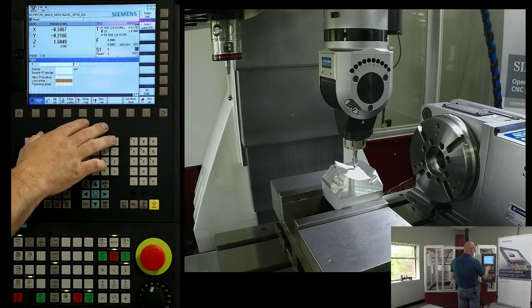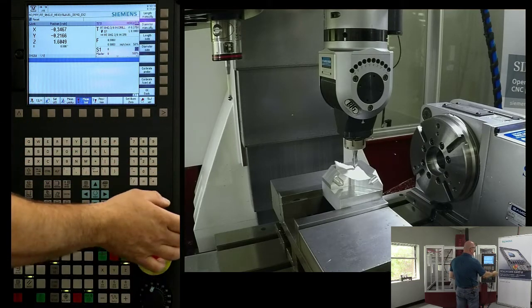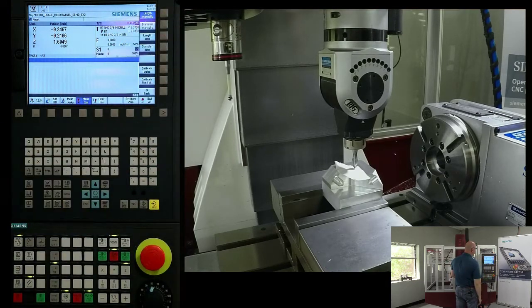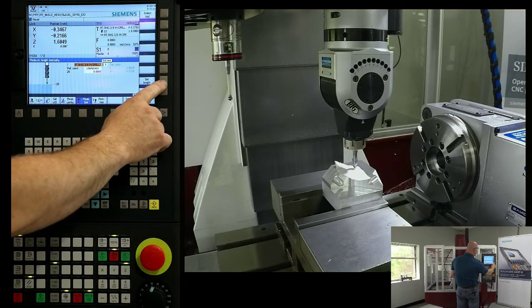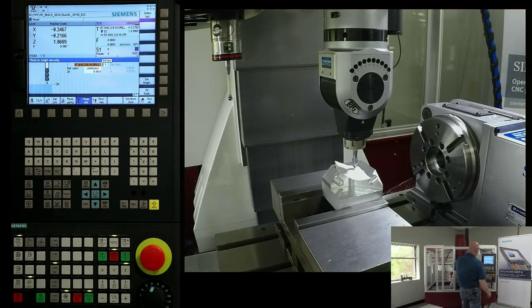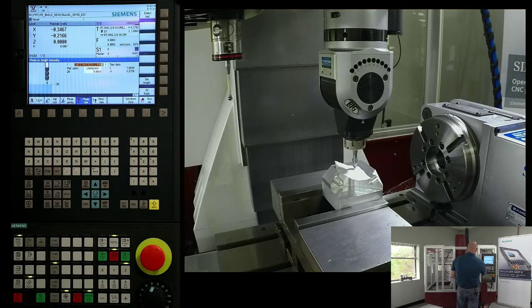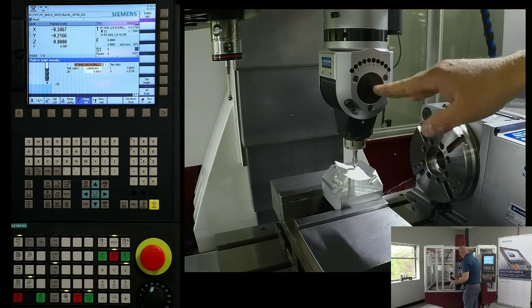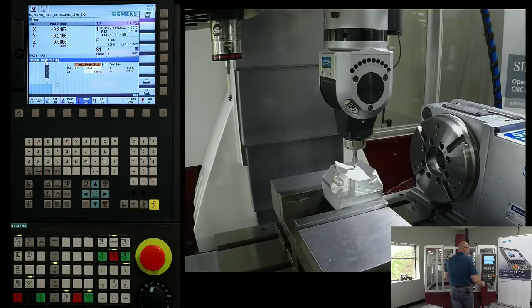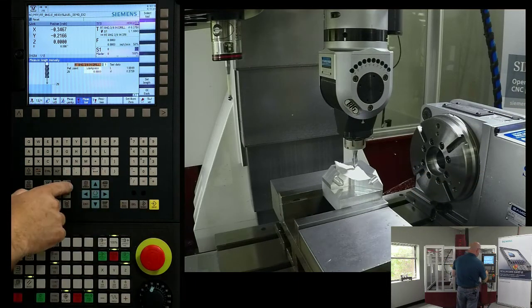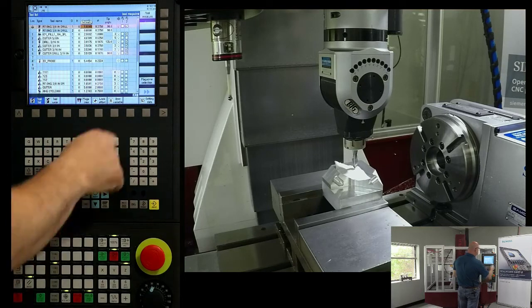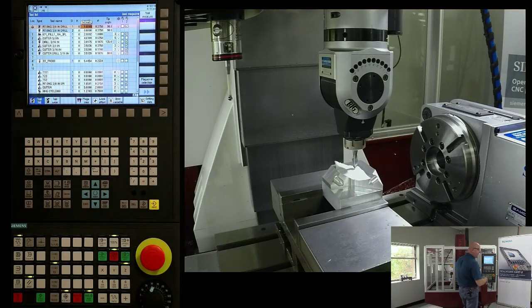Just like I would normally set up a tool, I go to Measure Tool, Length Manual, and hit Set Length, and it's going to calculate or compensate. What the system just did is it said, okay, since I know these other numbers, the 7-inch and the extra 3.8, all I had to do was figure out what's left over. If you go back to the offset table, I see I got a 1.6049 offset. So I would buy that that's sticking out about 1 5/8 inches.